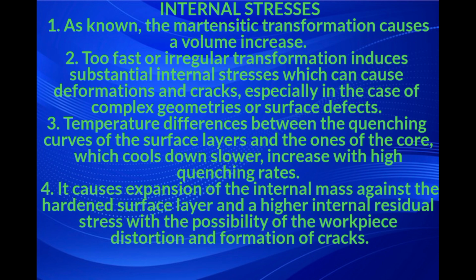After completing the induction hardening, the structure of the workpiece becomes martensite. And as known, the martensite transformation causes a volume increase. Too fast or irregular transformation induces substantial internal stresses which can cause deformation and cracks, especially in the case of complex geometries or surface defects.